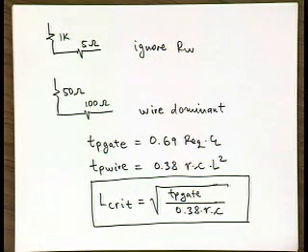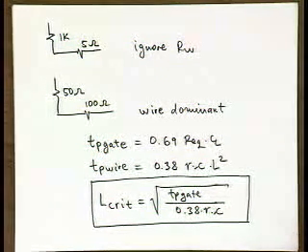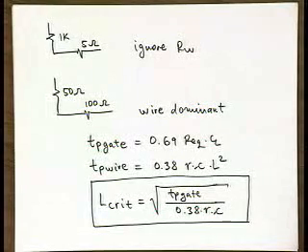If the opposite is true, that the rise and fall times at the input of the wire are much larger than the propagation delay, then your wire doesn't contribute much, and it can be treated as a lumped model. These are the two rules you need to look at before deciding whether to go with the lumped RC model or the distributed RC model. Okay?